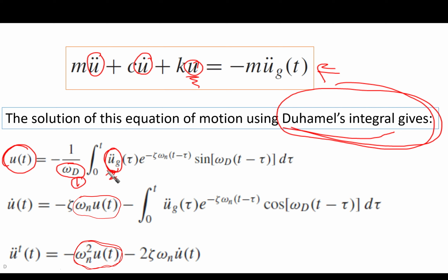This is the second parameter that is very important, the damping ratio. This is 3. The remaining parts are repetitions, so there is no way. So we have omega d or omega n, whether it is d or n. Okay, so no problem now, because there is a little difference between the natural frequency and the damped circular frequency. But anyway, here U of t is going to depend on the natural frequency of the system, the ground motion acceleration, and the damping ratio, right?